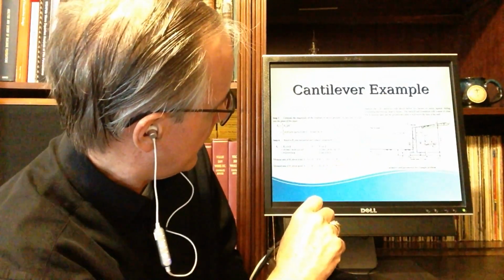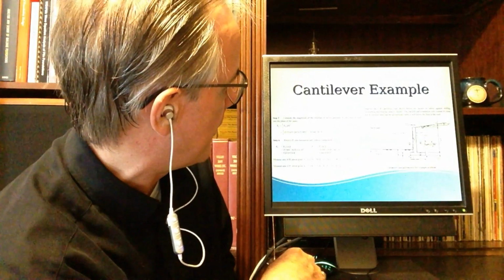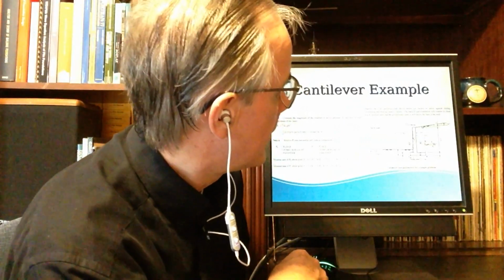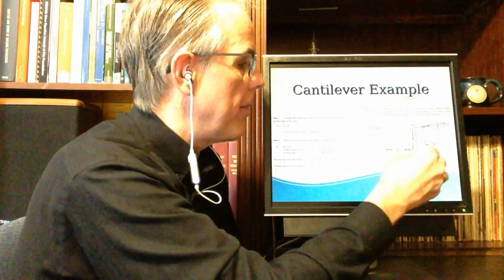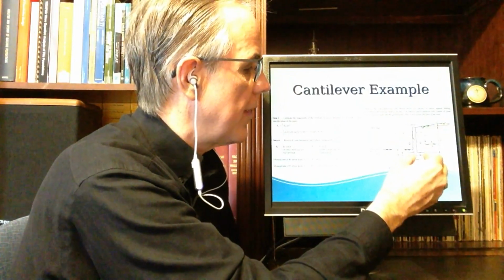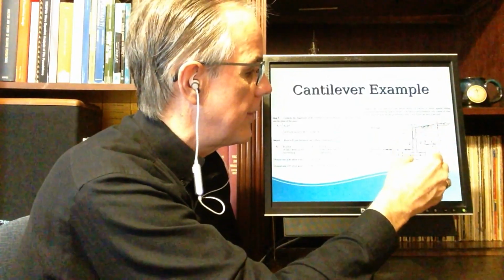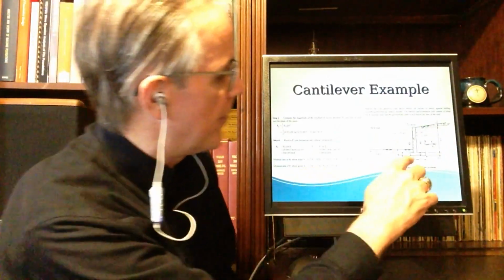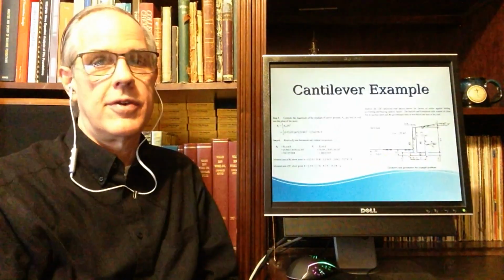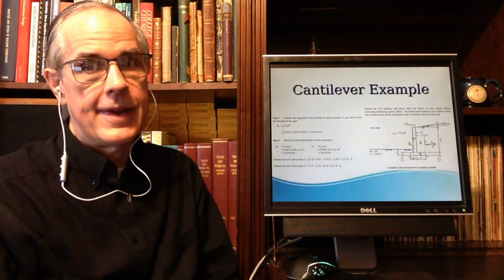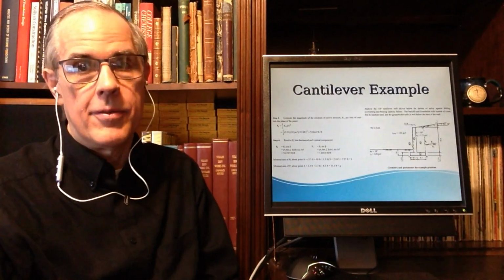And the moment arm is 7.27 feet, which is equal to the little b dimension. And then the vertical, as a moment arm, you've got this S and the eccentric, it's this right here. The distance from the toe to the heel, you have this, which is 2.3 times 2.3 8.5, this whole thing, which is 13.1 feet, which is the total width of the base of the foundation, which is subject to modification, by the way, in case you suddenly realize that either your bearing capacity or your overturning or your sliding doesn't work anymore.